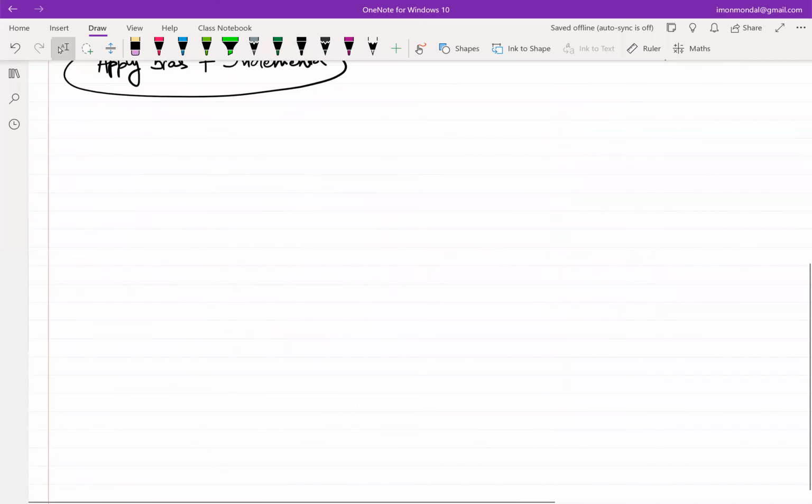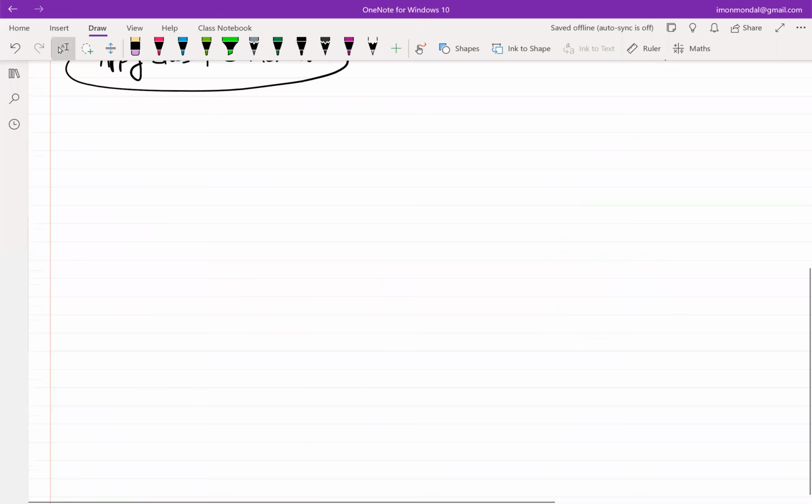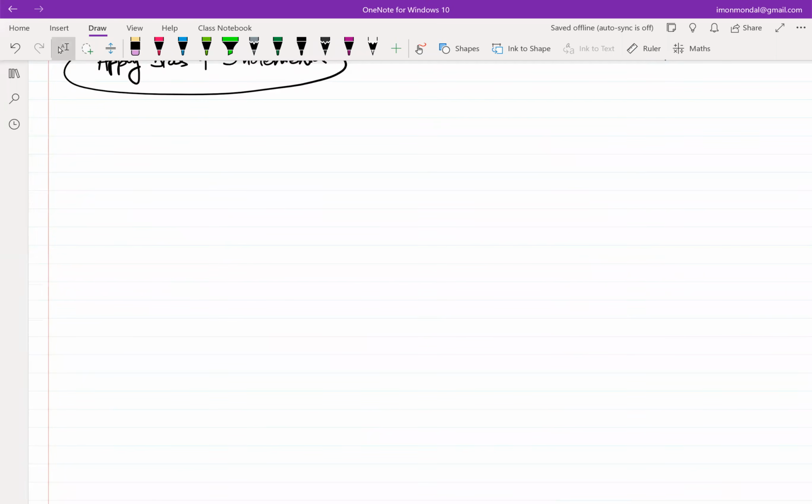Okay, so just before the midsem, we were looking into biasing our transistor with currents while applying a current source. And one of the reasons that we saw was if we bias a transistor using current sources, then the small signal or the incremental parameters are much more immune to changes with respect to ambient conditions, right? So then we saw that there are multiple ways of applying current sources and multiple ways of stabilizing your transistor based on negative feedback, right?